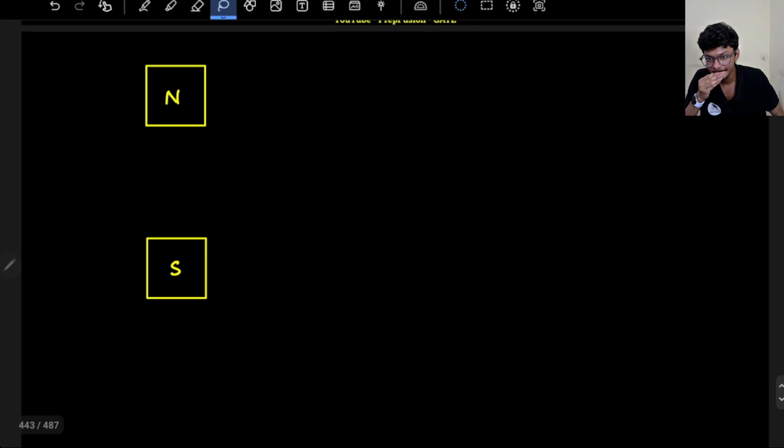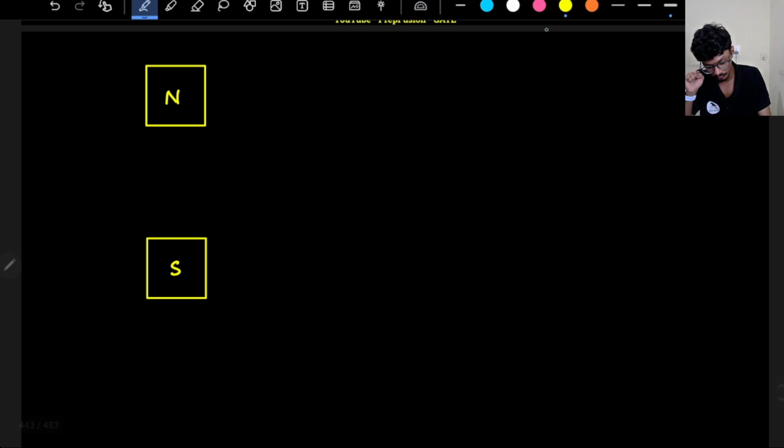Now if one of the coil sides is placed, like there are two slots, right? In one of the slots, this will be one side of the coil, and in the other slot the other coil side will be placed. So what is the angular distance? In case of theta m, mechanically and electrically both will be the same here because the number of poles is 2, so it is 180 degrees, right?